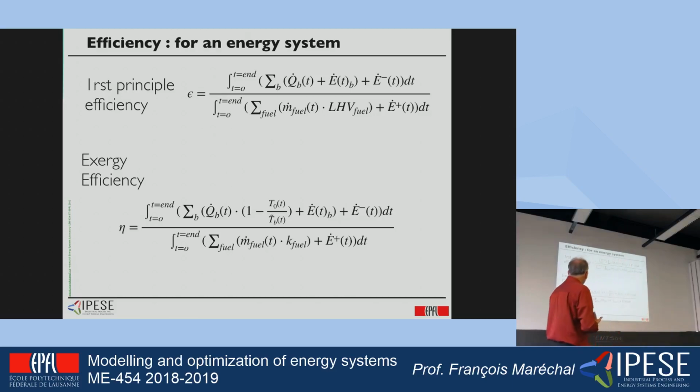Okay? On the other hand, this is the reason why we are going to introduce another type of efficiency, which is the exergy efficiency, in which, so you can see that I mostly have taken this formula there, but now I have added the exergy value, which is here, of the heat, which is the value in terms of electricity of the service that is delivered, considering the temperature at which I have to supply the heat, which is the one that you have calculated.